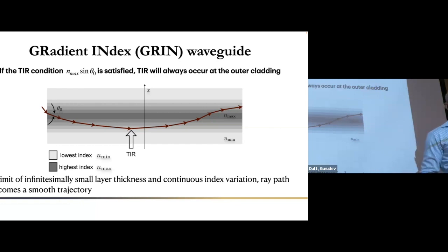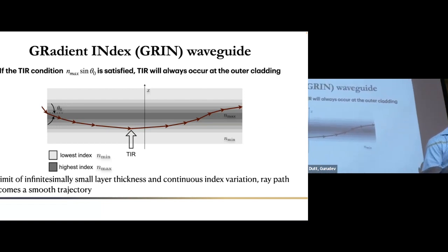In that case, we have the frequency cutoff. Yeah, that's all for single mode fibers. It's more relevant. For multi-mode fiber, not quite as relevant. Yeah, there is a frequency cutoff for them as well. In our limit, I'm just showing you an intuitive picture for what's going on in a multi-mode. Similarly, we can also talk about something called total internal reflection in a gradient index waveguide.